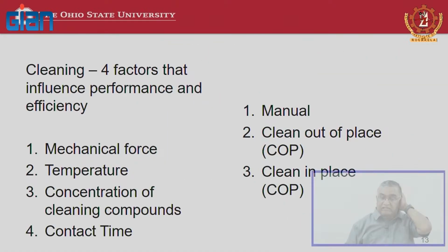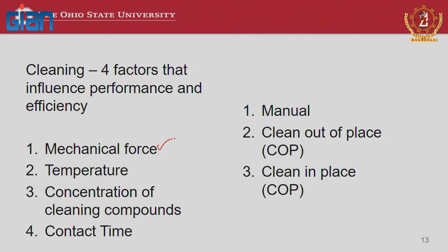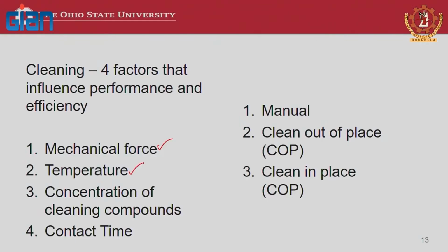So, there are 4 factors that affect the cleaning performance and efficiency. We said mechanical force. We talked about if you are using brushes, you mechanically scrape them. So, what type of mechanical force you use, at what temperature you are sending your liquid cleaning solutions, and what is the cleaning concentration of the compounds. Are you using very dilute, or are you going to have very concentrated? So, what is the appropriate concentration, and then how much contact time do I have, and so on.